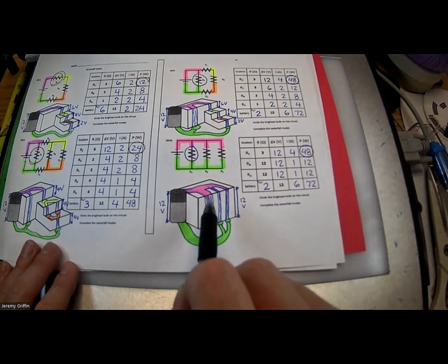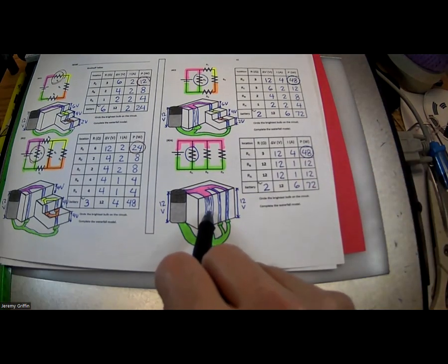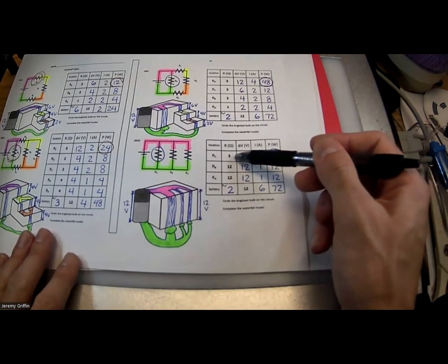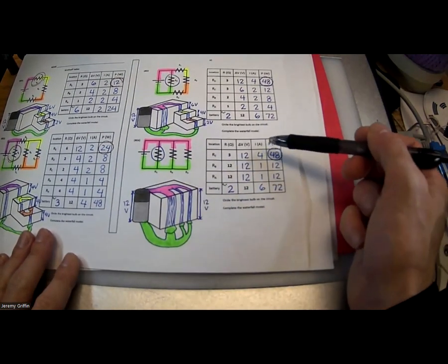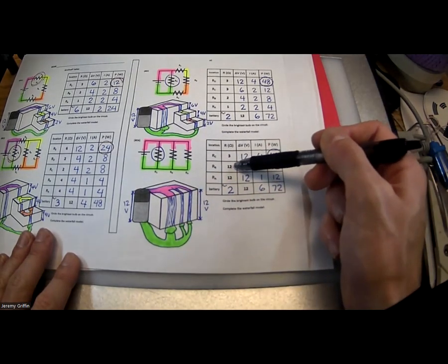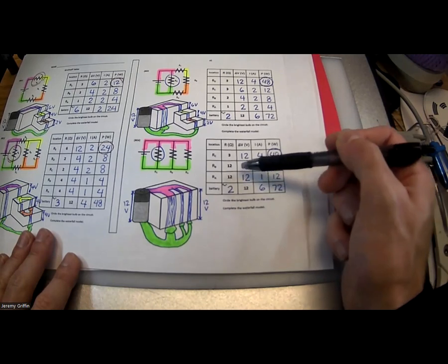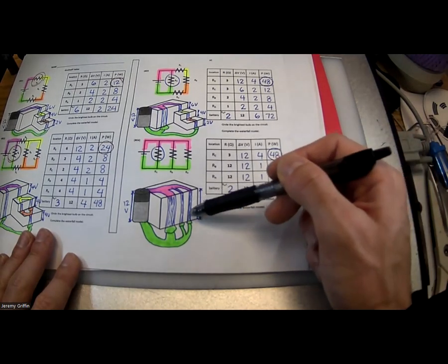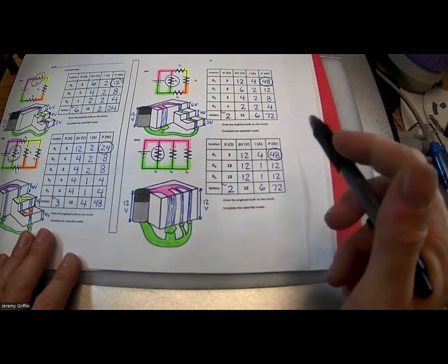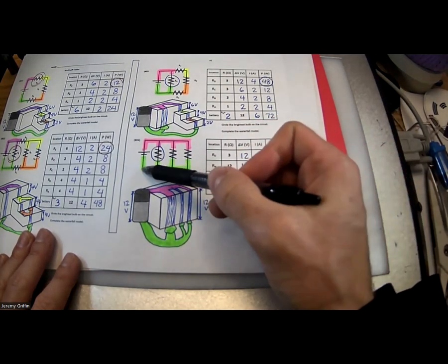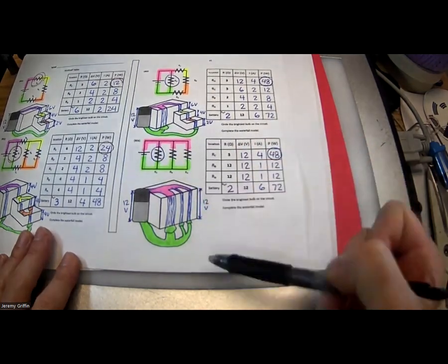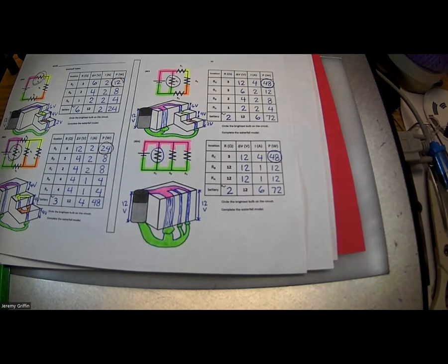Now, I might have a big fat waterfall here that represents a large number of amps of current, right? Which I do because I have a very small resistor. This guy has 4 amps of current going through it. Versus my 2 skinny waterfalls, well, that's because they're huge resistances, right? 12 ohms, so I've only got 1 amp going through each of those, right? But they're all the same voltage drop, right? They're all like 12 volts, right? And that's Kirchhoff's loop rule. Up 12 volts, down 12 volts. Up 12, down 12. Up 12, down 12. Okay, guys get that?